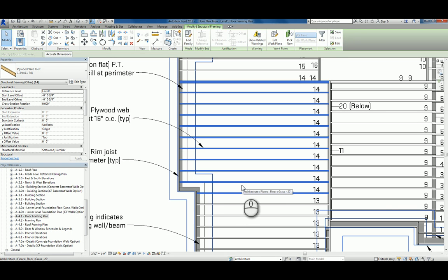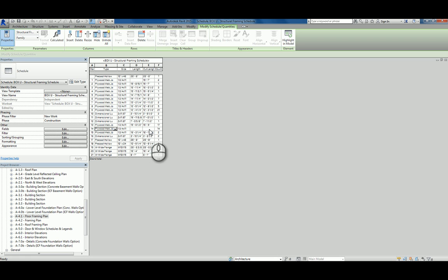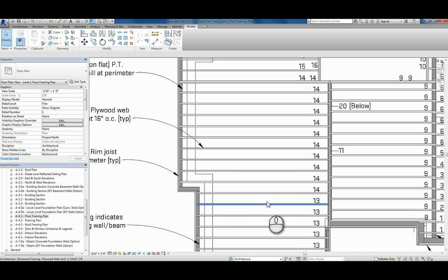So the setup is, the length is in the Revit system family where it says this would be the overall length, and then you'd end up from grip to grip. The cut length would then be the grip to grip minus the setbacks. So the length really doesn't tell you anything. I think the length is in there because it's in there for everything, like a wall and everything else. But I'm not sure what else the length itself really gives you. But I haven't seen this before where it groups together these ones that are actually a separate length.